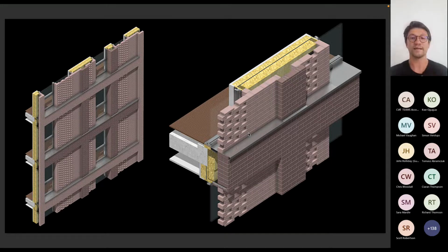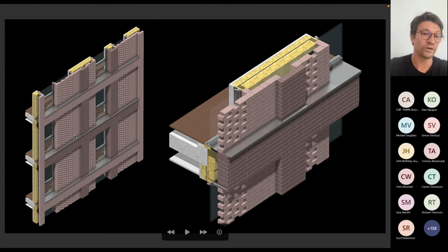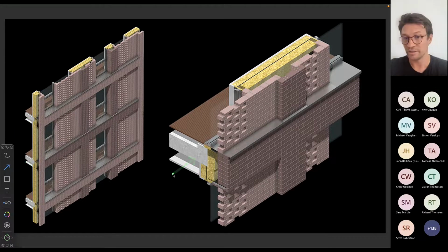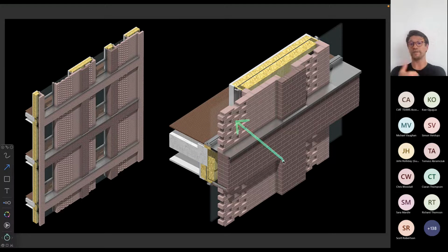And that actually drives the project to be masonry veneer with brick support at every floor. There's a requirement to have a downstand to accommodate the shelf angles and the cavity closers, and to accommodate the hit and miss stack brick, which also serves as the solar shading and potentially ventilation.